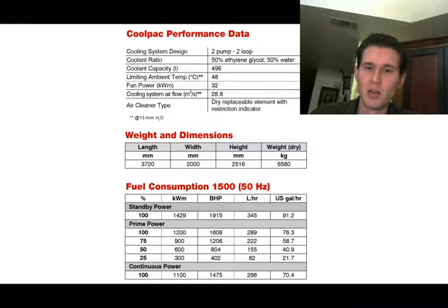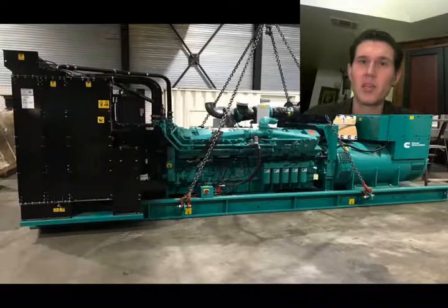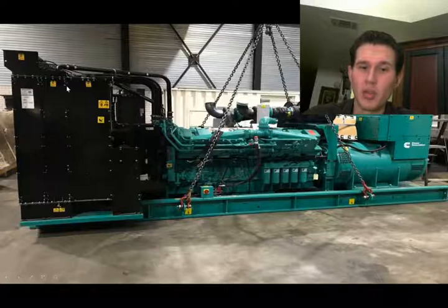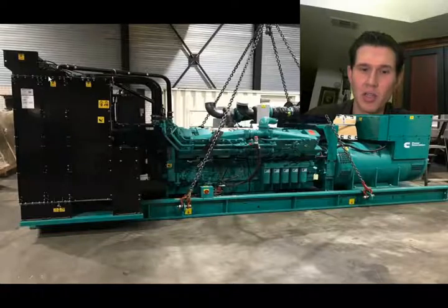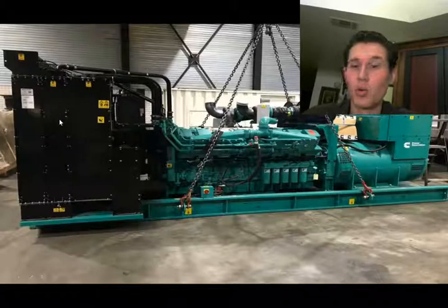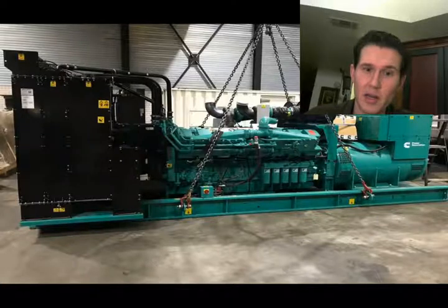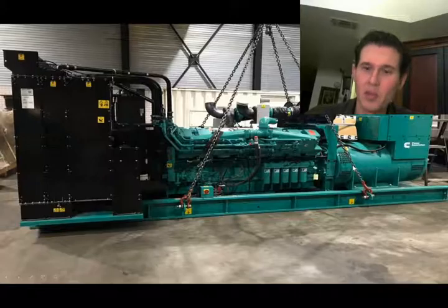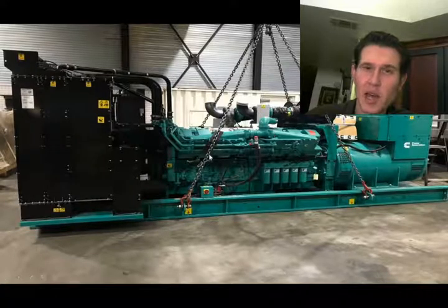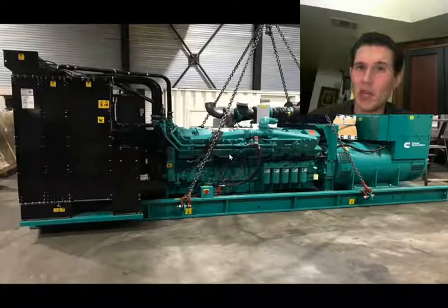heat exchanger. There are two ways to measure the energy going into the heat exchanger. One, we do a control boundary around the heat exchanger, and that will tell us how much energy is going in if we measure how much is coming in through the pipes. Or two, we do a control boundary around the motor, which means we have to account for the cold air going in, the hot air going out, the energy going to the generator in form of mechanical, the dissipation of heat through the actual motor, which means radiation and convection.